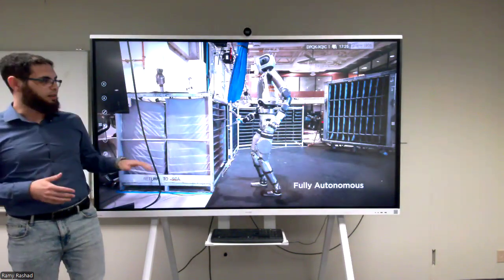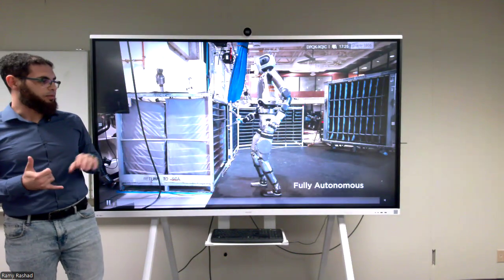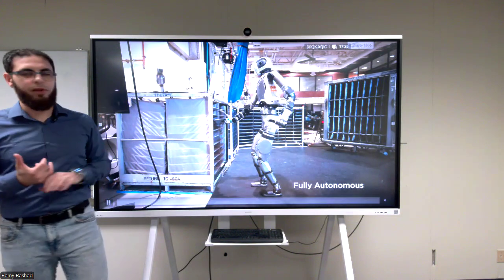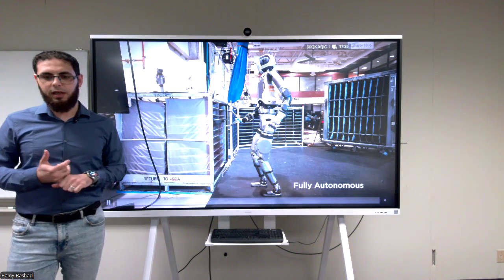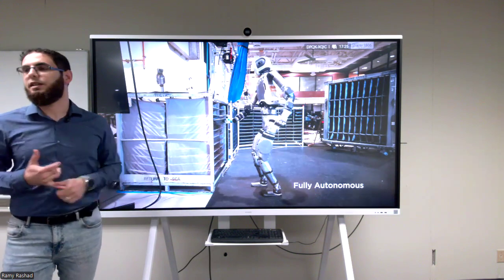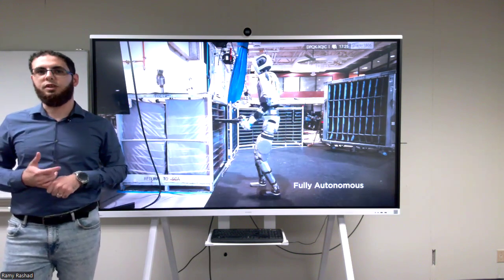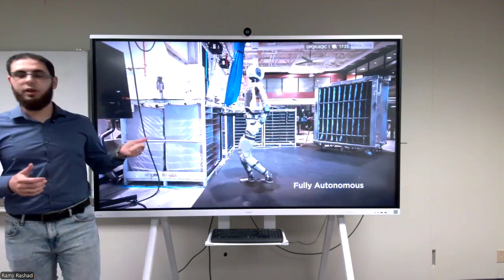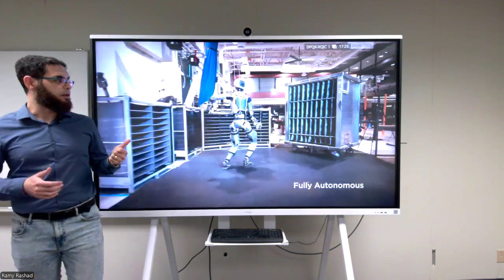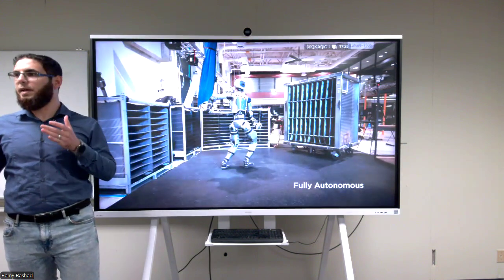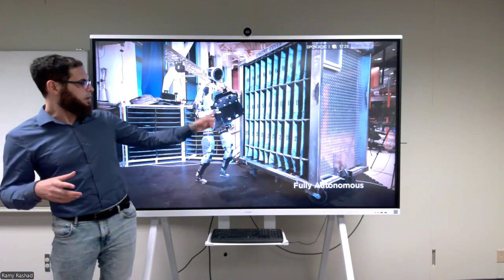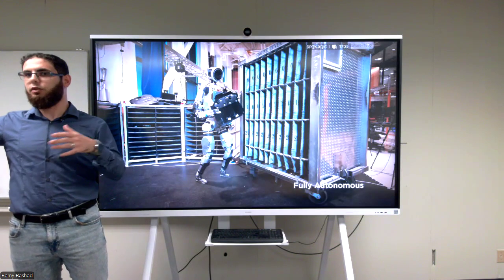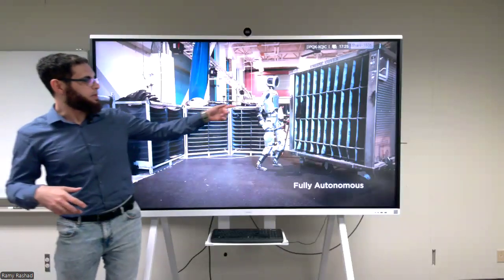This is the video stuff. Hopefully it will be okay. Floating base manipulators are usually the interesting stuff. Most of you chose in your projects some type of floating base manipulator. Humanoids are one of them. So a humanoid is a floating base. You can think of the floating base as maybe the torso of the robot, and it has multiple manipulators attached to it. One of them is the right hand.